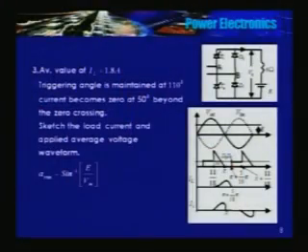And also determine the value of E. E is not known. Again, where does one trigger the SCR, or if I apply a gate pulse, from where onwards will it start triggering? Alpha min should be equal to sin inverse of E divided by Vm. E is not known.